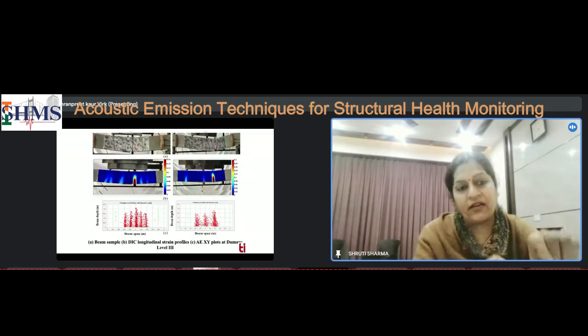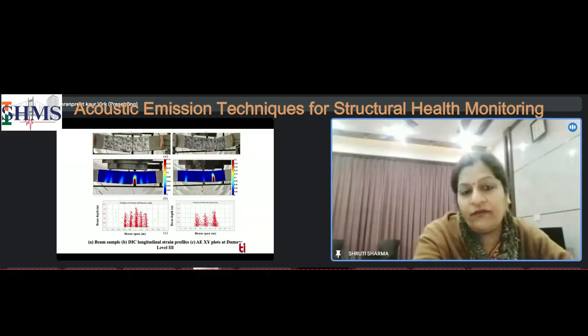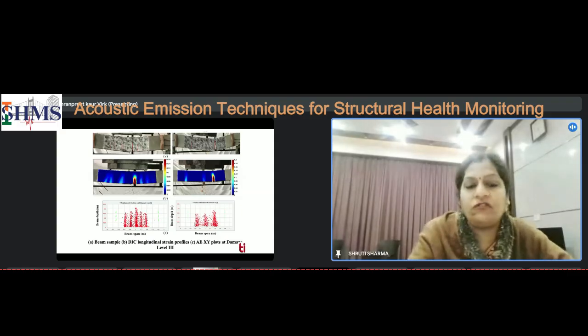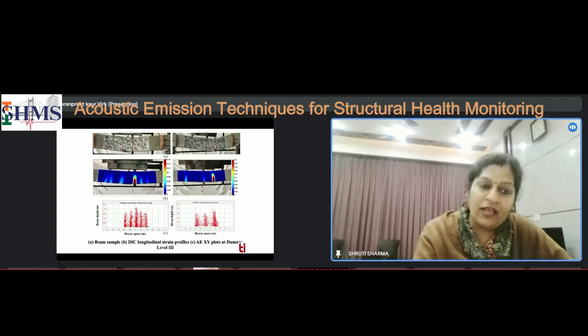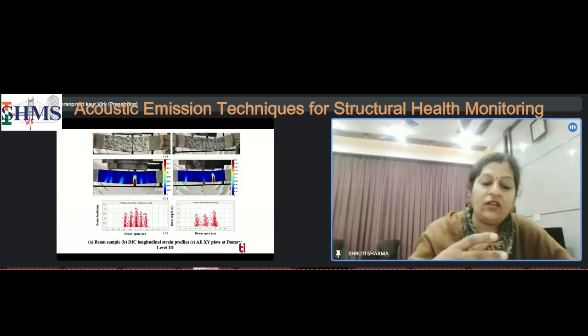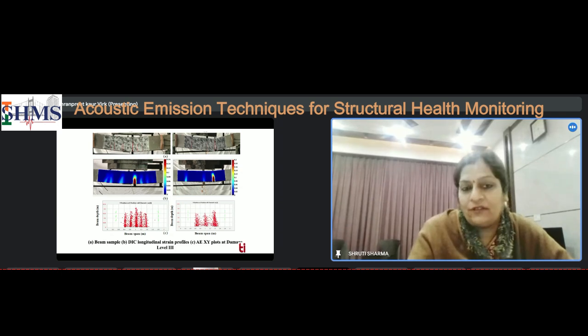Where we expect the cracks to occur, of course, it's a tensile failure in the steel reinforced beam. At a sudden failure, a big crack is observed in the GFRP reinforced beam on the right hand side, and the AE plots are showing exactly where we see the failure finally taking place. Even DIC is showing the correct thing, but AE gives you the dots. You are seeing the dots appearing on the screen. So the beauty of AE is this.